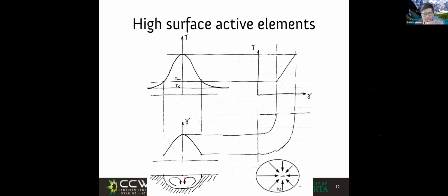Let me tell you more, something very interesting. Modern stainless steels are made with vacuum furnaces, with such a high level of purity that they have close to no sulfur and close to no oxygen. You know what? Modern stainless steel sometimes has a problem of penetration because these Marangoni flows go out and don't go in, and the welds have pretty poor penetration.